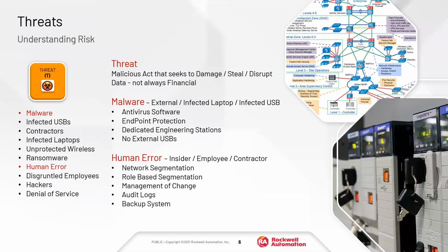Another potential option here, if we're talking about malware, is having dedicated engineering stations. Some of the customers that I deal with have dedicated engineering stations that they use for all of their development, whether it's for internal engineering or external. Third-party contractors that come in would be forced to use a dedicated engineering station, which removes external or unknown assets. So I&E laptops, computers, servers, any outside source that you haven't been able to validate, it removes that by forcing those external contractors to use a dedicated system that you provide.